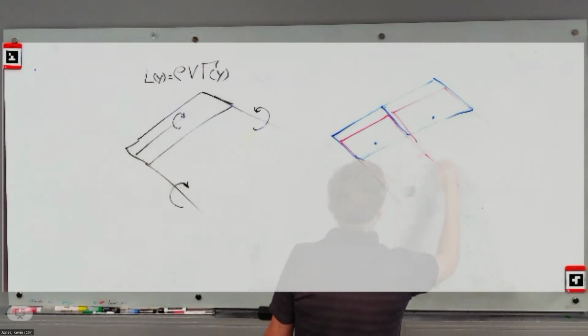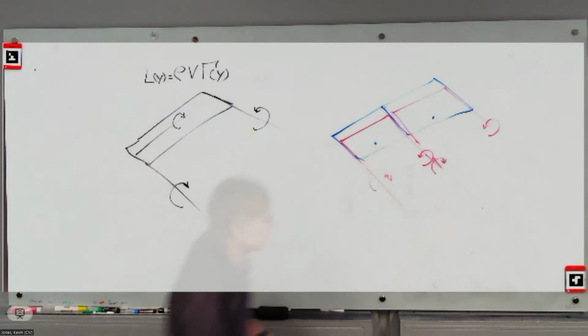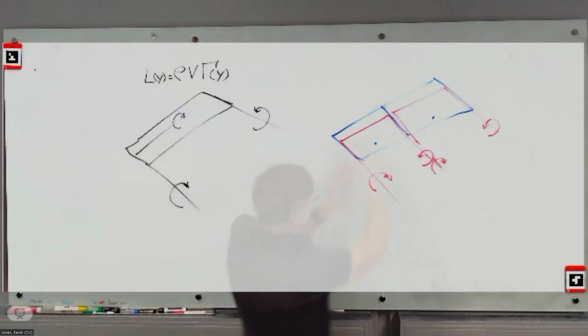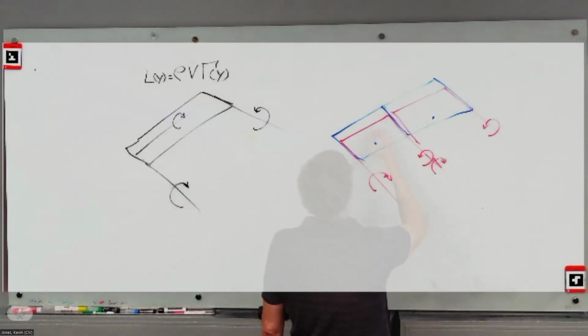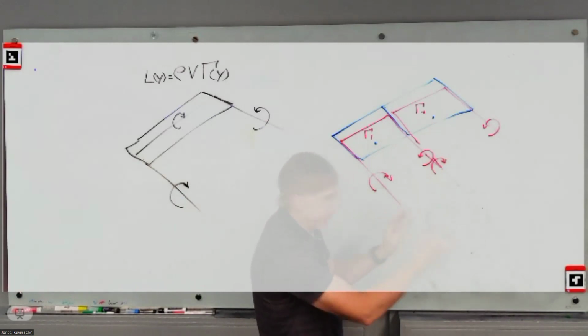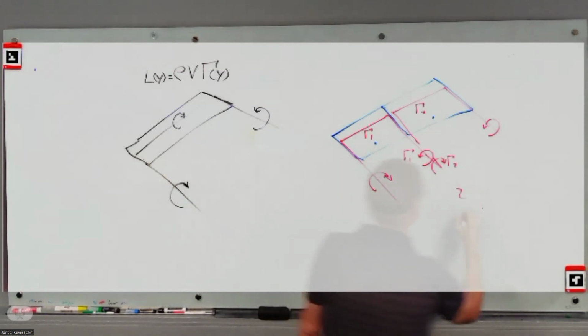This one gets the other direction. And these two, this is the tip. This one's going to have less lift than this, right? Because it's on its way to dropping to zero lift at the tip. And so this is exactly what you're constructing inside of the VLM method. And so this is gamma 1, 2, and these two, they're actually exactly on top of each other. So they partially cancel each other out, right? So the net change here, the net strength of this is gamma 1.